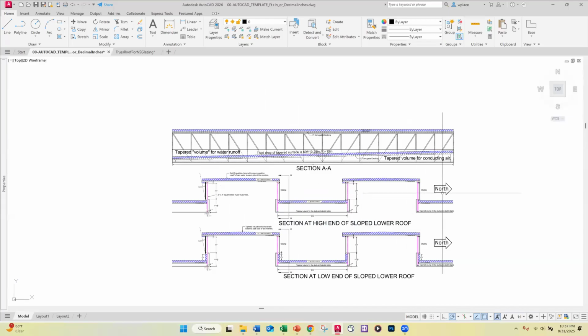Okay, this, by the way, is north. So this is the north-facing glazing, which has no overhang to speak of. And then this is the south-facing glazing, which has a little bit of an overhang to protect it. Now, I mentioned that if we only have south-facing glass and we have, say, a sawtooth roof, then the profile angle for that overhang is greater.